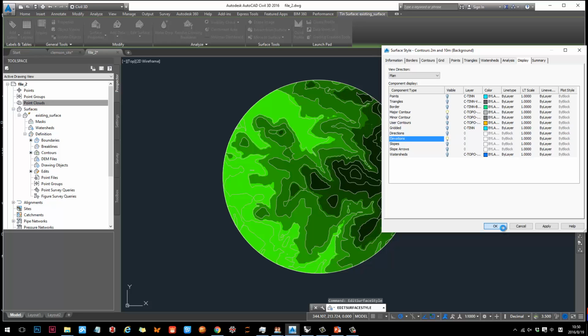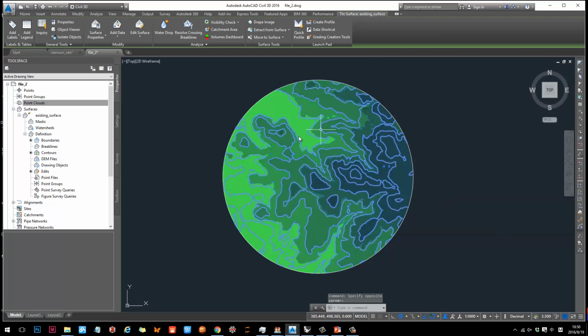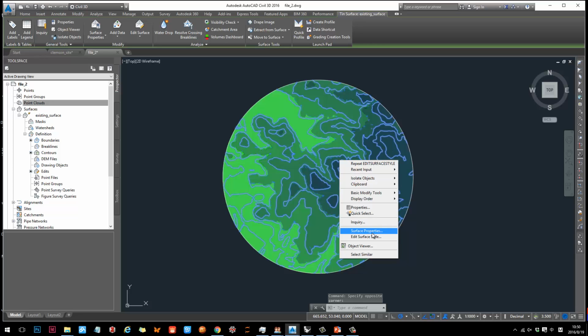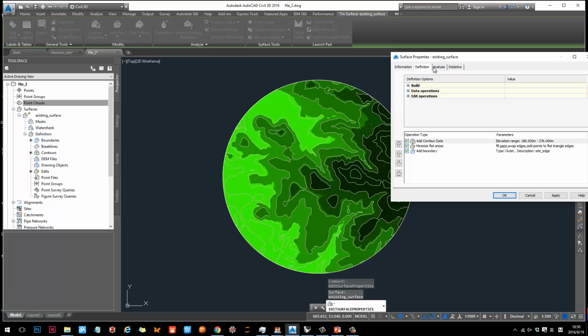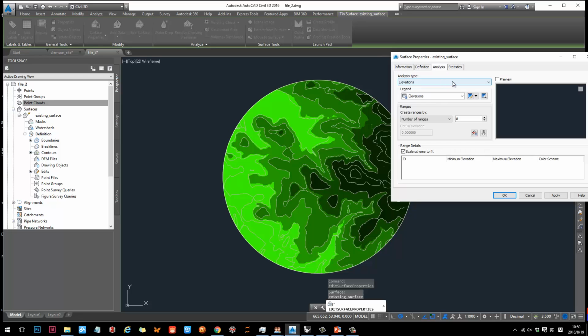Okay. By the way, for elevation, you can actually change the elevation by create service properties, and there's an analysis tab. There's 4 tabs here, right? The analysis tab is really important. You can check. So there's all kinds of analysis types, right? What you do is just go to elevation, right? Then you can select how many elevations I want. I think 8 is a little bit less. You can create up to like 14. And what you need to do, just remember this button and click it.